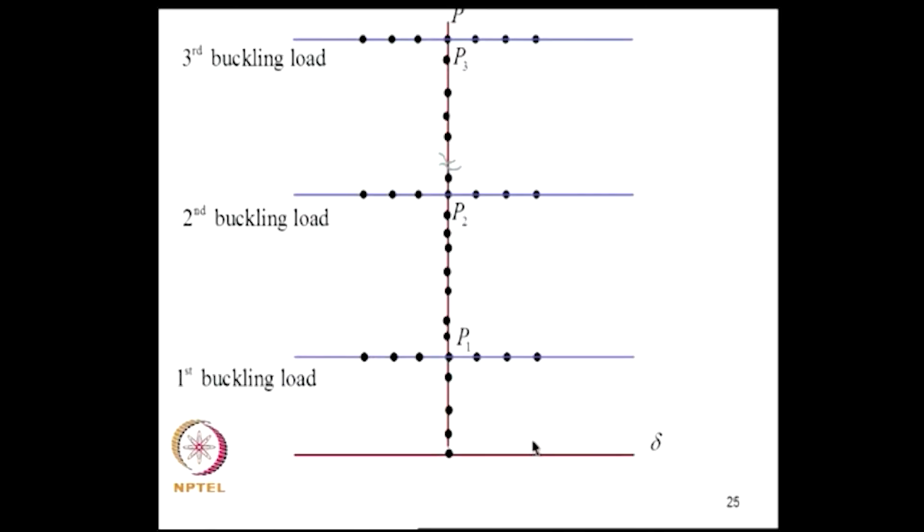So, now equipped with this analysis, we can redraw the load deflection diagram now. So, here if P is less than P critical, our load deflection path will trace this branch, and as P becomes Pb is equal to P1, as you pluck the beam it will occupy different positions, and if you go on increasing the load, there are other branches that are possible. So, it turns out that there are infinity of P criticals possible, and the load deflection diagram will have infinite number of branches.